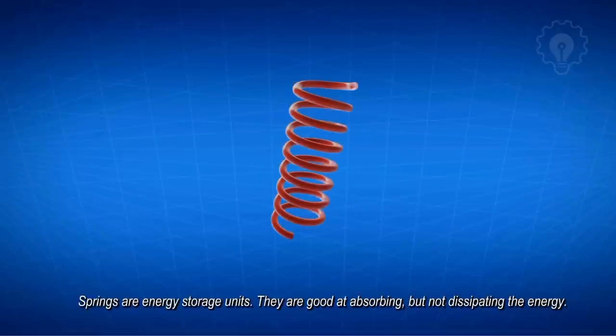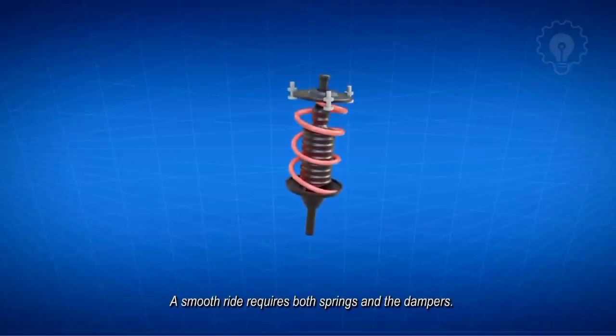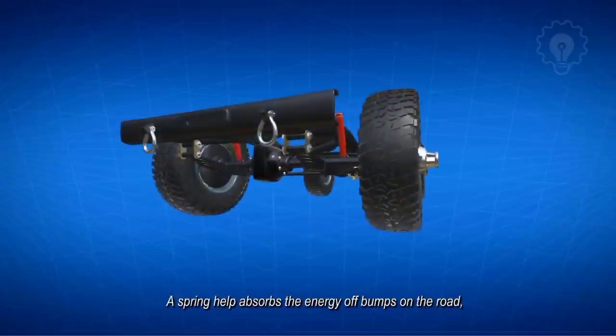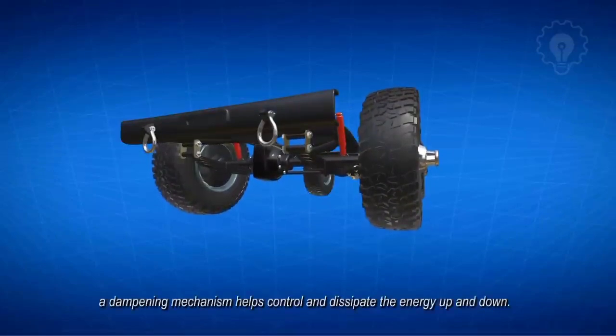Springs are energy storage units. They are good at absorbing, but not dissipating the energy. A smooth ride requires both springs and the dampers. A spring helps absorb the energy off bumps on the road, and a dampening mechanism helps control and dissipate the energy up and down.